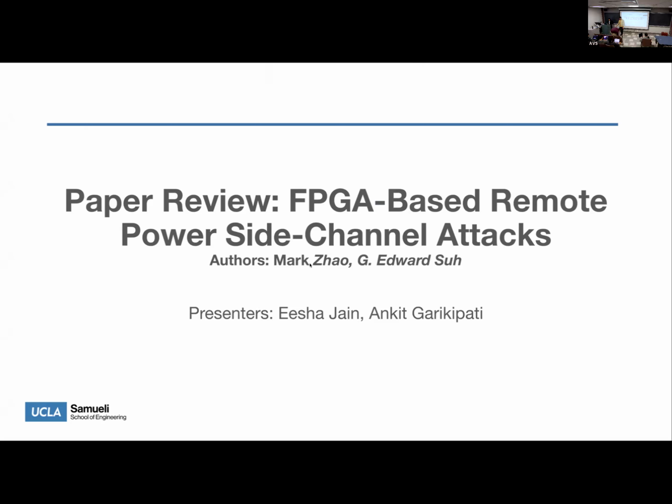And before we move on, do you know why we cannot just listen to the Bluetooth packets instead of doing this? Why not just pick up the Bluetooth packets directly and listen to that? Anyone want to say? That's not encrypted. They are encrypted, right? So basically what they do is after the encryption, once the packets are decrypted and then you start actually looking at them, its emanation is there at that point. So that's why you can actually leak this.